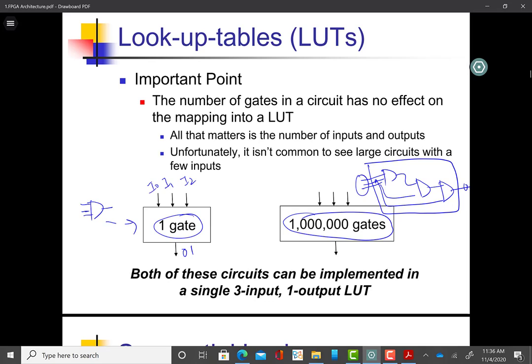So this is all about lookup tables and how they are implemented at the circuit level, how they operate in different modes, how they can be used in single output mode, and how they can be used in dual output mode. All this is very fundamental and very important for understanding what we can call the workhorse of the FPGA. The lookup table is the workhorse. It is the basic way for FPGAs to implement combinational circuits. The material we covered until now is very important to understand if you want to understand the FPGA architecture and its working.